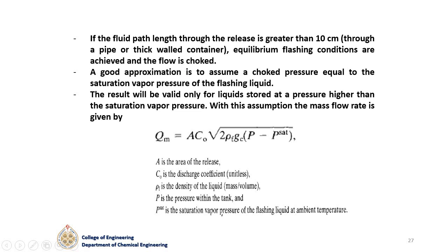Because the flow is maximum, I can assume that the choke pressure equals the saturation vapor pressure of the flashing liquid. And this is why I can get this equation here. This is the equation you need for calculations if we have flashing.